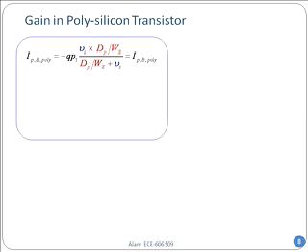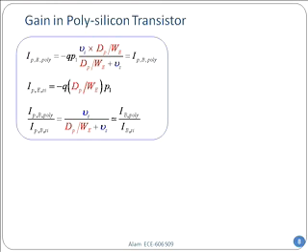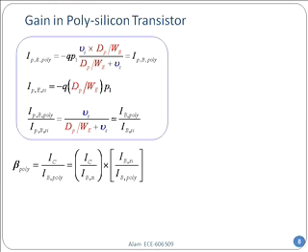So the hole current is essentially all that there is to the base current. Why is that? Because the amount of base current flowing to the collector is minuscule. Do you agree? Because base-collector is actually reverse biased. So it has a huge barrier on the collector side, but a very little barrier to the emitter side. And as a result, the base current is essentially entirely due to the flow of holes. And this is something I have already shown you in the last slide.